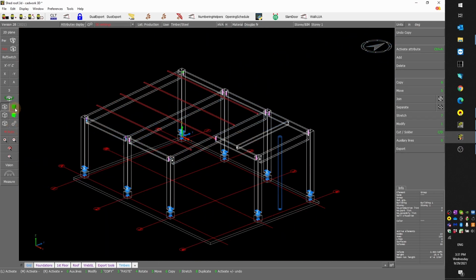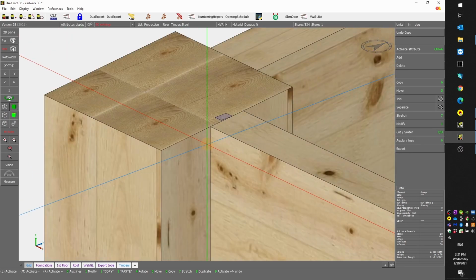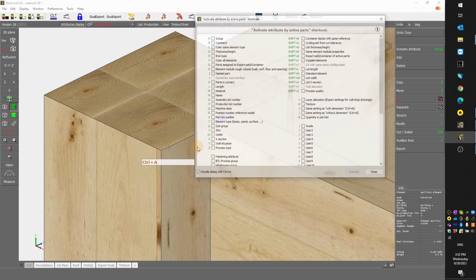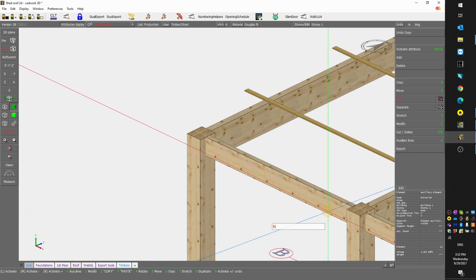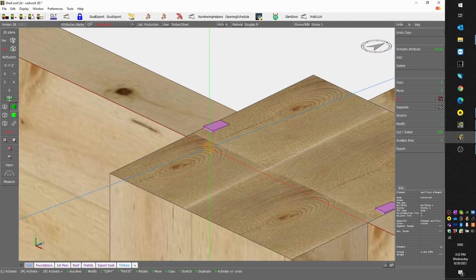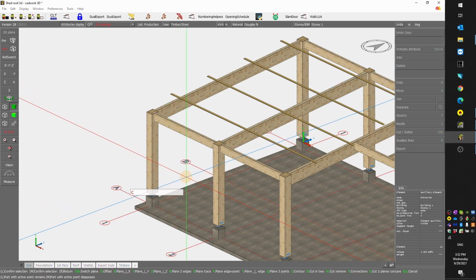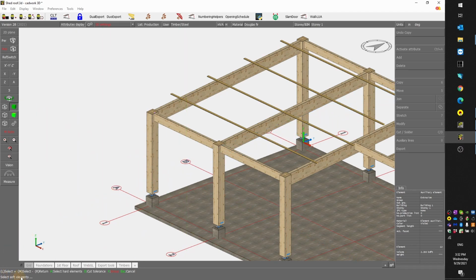So now the next step is to cut out the dado. So I need to select only the cutting part. So I make sure join is red. So I left click on the square here, and then I do Control A N to activate all the extruders, and I do C to cut, W to cut active hard and soft, and now Cadwork is asking me to